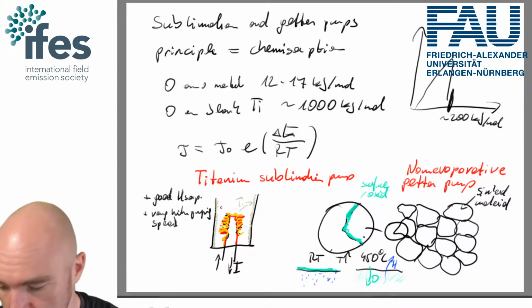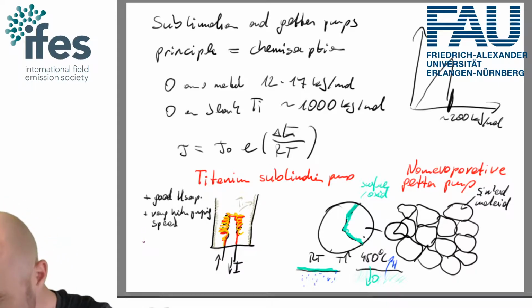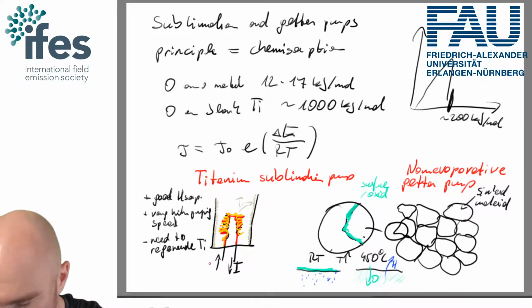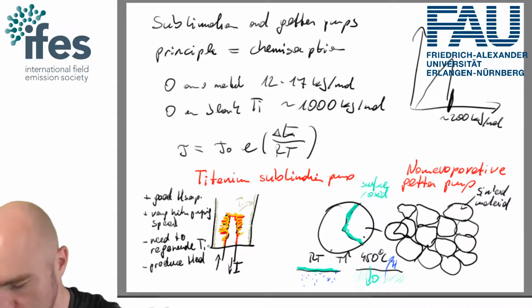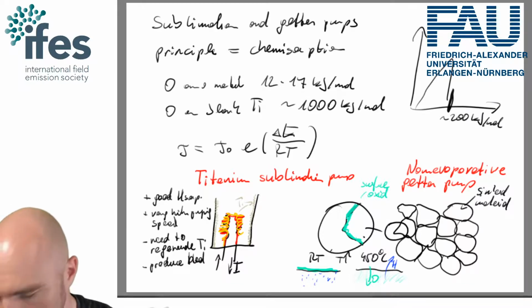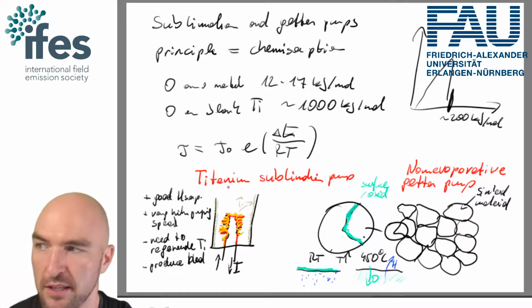Very, very high pumping speed. The minus is that you need to regenerate the titanium layer, and this means you produce heat. Because you've got a hot filament here at the bottom, which means you produce heat that you put into your system.